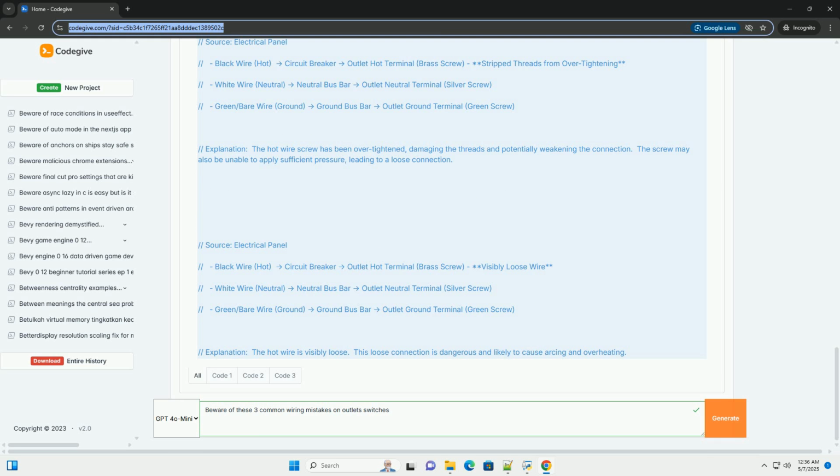Code references, NEC examples. NEC 110.3(B) requires electrical equipment to be installed and used in accordance with the manufacturer's instructions and markings. This includes tightening torque requirements for screws. NEC 110.14(B) addresses the tightness of connections and states that connections shall be torqued as specified in the manufacturer's instructions.